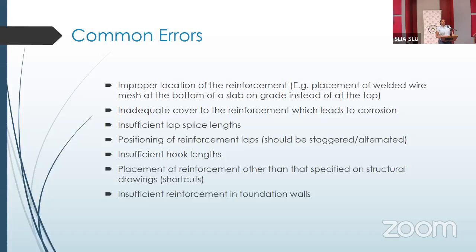Now, when that happens, you're making your reinforcement vulnerable, because you have things like driving rain. When the wind is blowing, it's going to be pushing or forcing that rainwater into the pores of the concrete. Yes, we can design the concrete to be fairly dense and fairly impermeable, but the fact remains that we still have pores where water can get into the concrete.